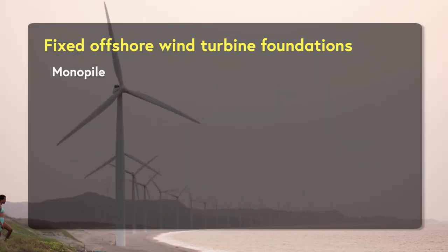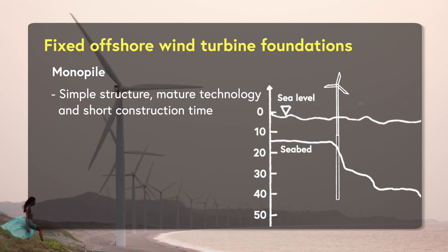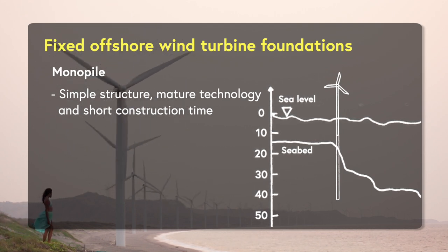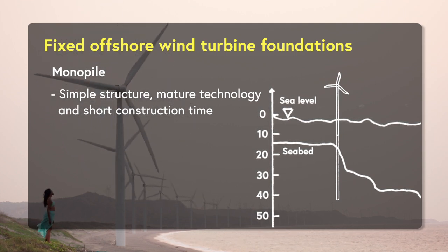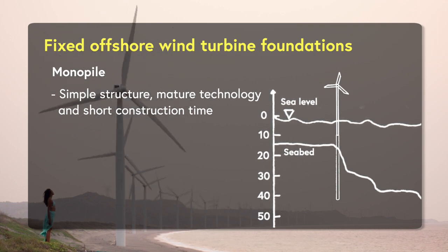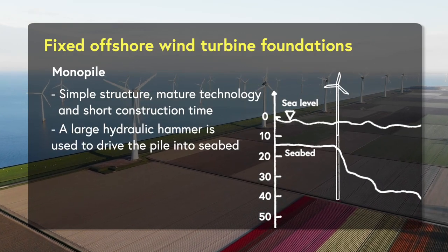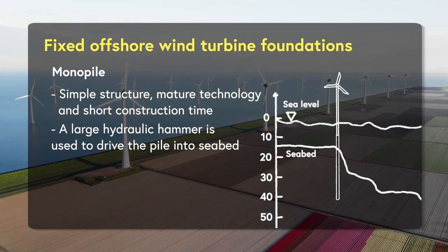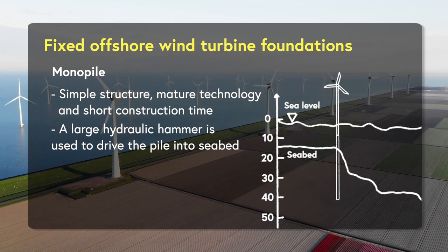Okay, the first type of foundation is called a monopile foundation. It's very simple, and the design is just put a very big column into the ground. So the column will hold the wind turbine. As you can imagine, because we are using one pile and it has to hold the whole structure, the pile has to be very big. And when we install this pile, for example, we can use hammer to drive it into the ground, or use drilling, or use vibration, which means I need a very big working ship to drive this pile.